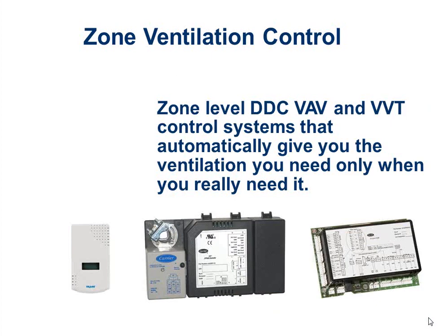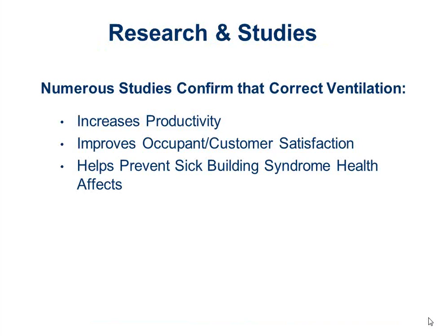At nighttime, I can go fully down to 0 and shut all the zone dampers and air handlers for ventilation purposes. And no, you don't have to do any special flush in the morning there, Greg, for the building. That can be taken care of by the CO2 sensors when people come in, although many of us do like to program a 15-minute flush sequence to bring in the full ventilation air in the morning just because it seems like a logical thing to do. But technically, you don't have to do that.